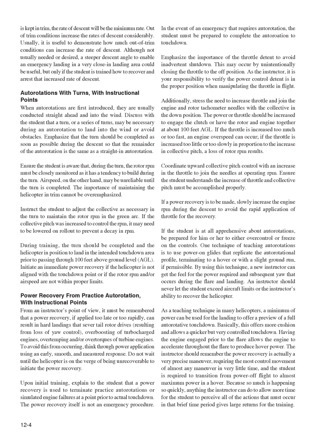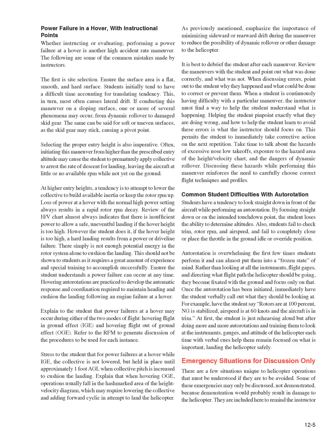Power failure in a hover. With instructional points, whether instructing or evaluating, performing a power failure at a hover is another high accident rate maneuver. The following are some of the common mistakes made by instructors. The first is site selection. Ensure the surface area is a flat, smooth, and hard surface.